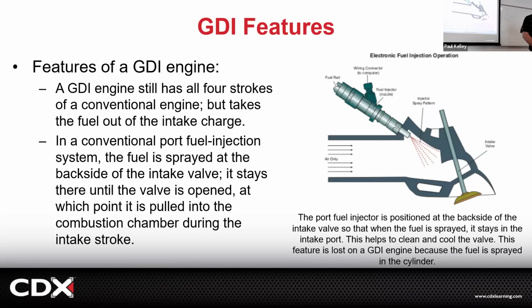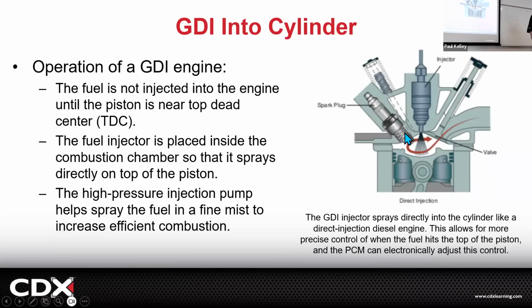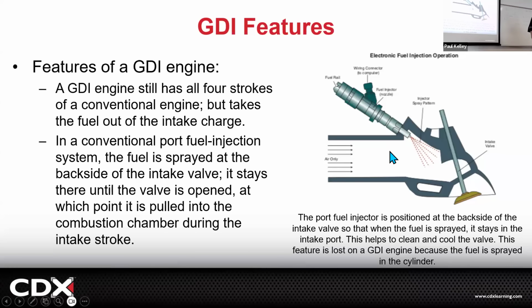And additionally, here's your port injector, right? Air would mix with fuel, and droplets would get stuck all over these little places. And it was decent. With a carburetor, by the way, the fuel came from way up here at the intake, so there was fuel sticking to the manifold and all sorts of stuff. With port fuel injection, we were pretty close to the valve. With direct fuel injection, we're after the valve, right? If I just compare, here's your direct injector. All of this fuel is going to get burned. With port fuel, most of this fuel is going to get burned.